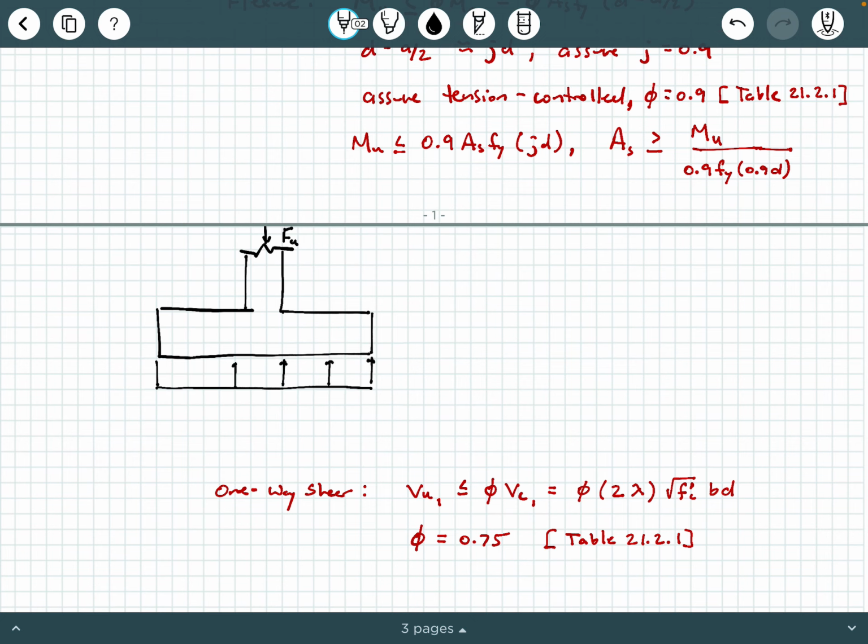And if everything is concentric and centered, you're going to get a sigma sub u. Again, this has your LRFD load factors in there. So for example, 1.2 dead plus 1.6 live, all right? And what you're doing here is you are looking at MU at a critical section, okay? So where is this MU occurring in this nice little figure that I drew here?